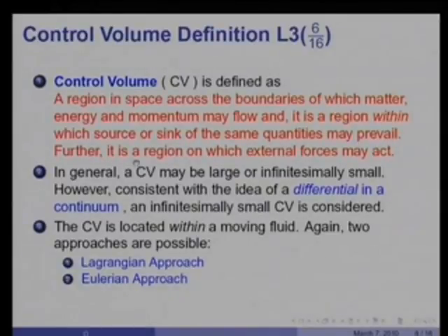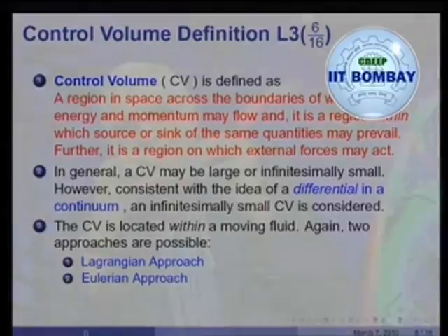Further, it is a region on which external forces may act. So imagine a very tiny fluid element inside a fluid flow. Then we are saying that in this fluid element, energy will flow in and flow out, mass will flow in and flow out, momentum will flow in and flow out, and it's an element on which external forces may act.